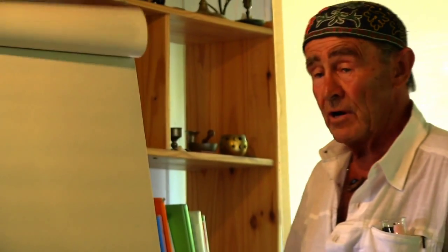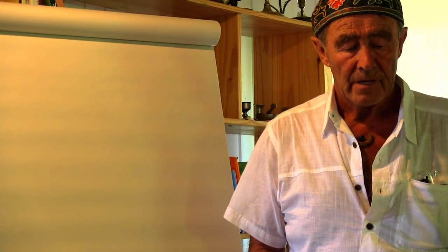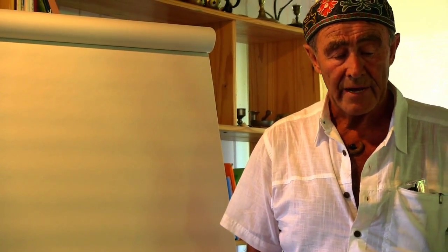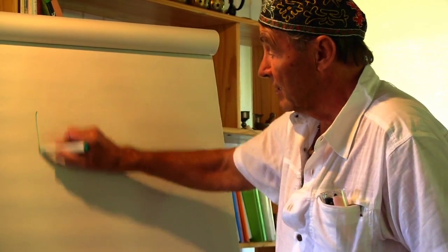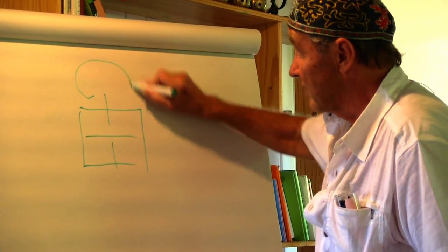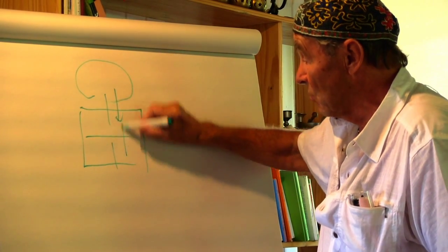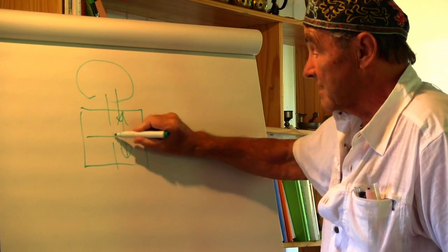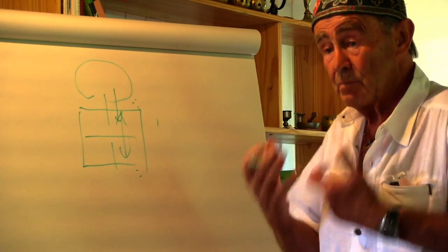We have spoken about the Stirling. If you understand the principle of a Stirling as a black box, I call it a thermodynamic transistor. Why? Because what we discussed at length, this displacer piston, which takes a small fraction out of the energy of the flywheel to move back and forth, is triggering a much stronger heat difference potential in power.